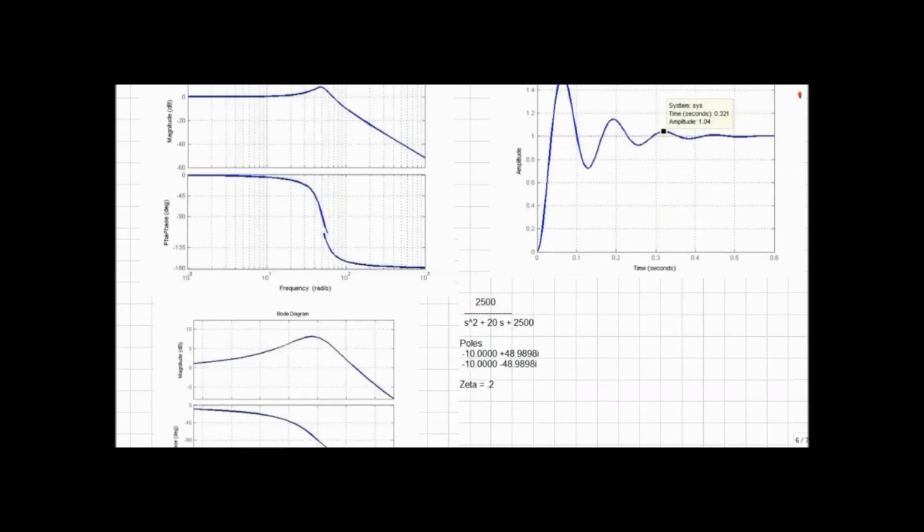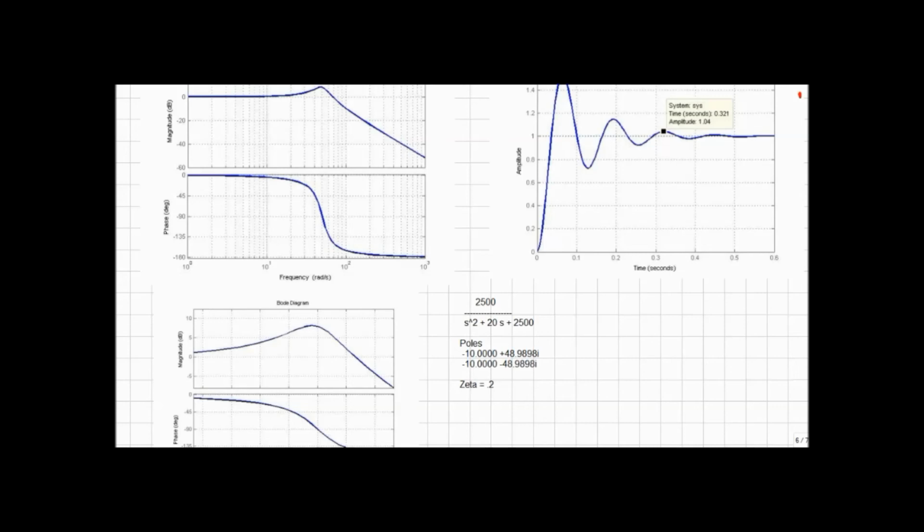Now remember, basically the magnitude of G(j omega n), the amplitude of the transfer function at omega n, divided by the amplitude of G(j0), the amplitude of the transfer function at a frequency equal to 0, comes out to be 1 over 2 zeta, because when you put those two equations one on top of the other and start substituting in omega n's and zeros, you get a lot of ones and a lot of zeros, most of the terms fall out, and all you're left with is this 1 over 2 zeta. So that's that equation.